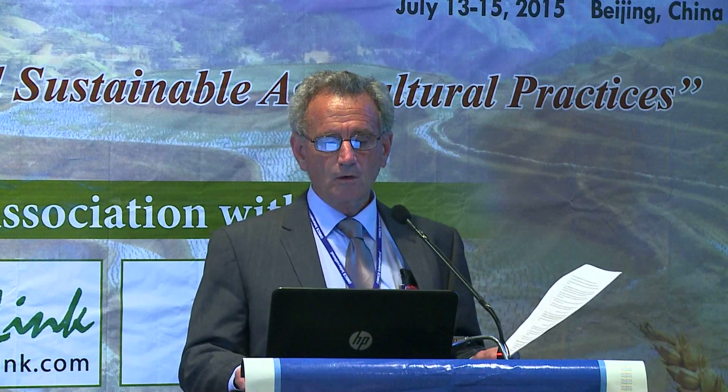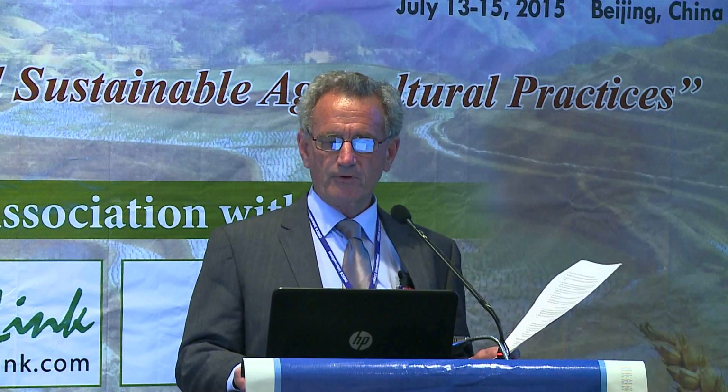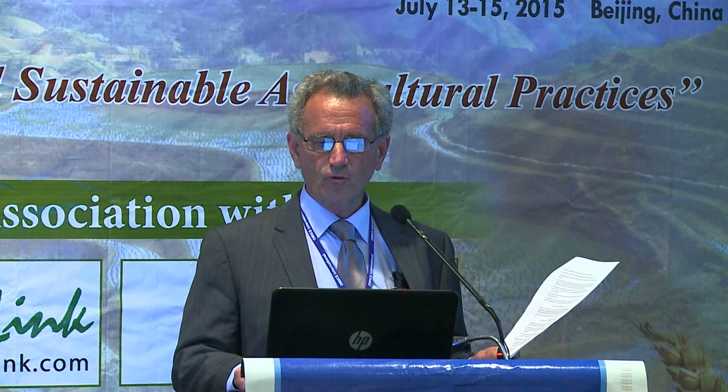Step one: one needs to estimate the net evaporation in millimetres for the location for the hottest dry month of the year. For example, in Adelaide, the net evaporation is about 267 millimetres in January. This information is available from the Bureau of Meteorology.